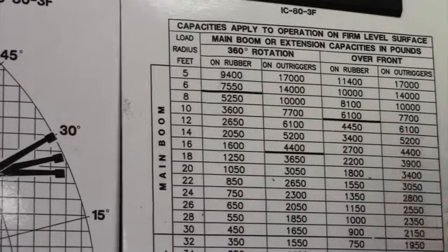That means that if you overload, the crane is not going to tip over. The crane is going to be structurally damaged if you overload it. This represents the crane's structural capacity. When you go below the black line, that is limited by the tipping capacity. When you're on outriggers, when you're at capacity, you're at 85% of tipping capacity. So anything that is below the black line, if you overload the crane, you're going to tip it over. Anything that is above the black line, if you overload the crane, you're going to damage the crane itself, bend the boom, and so on and so forth.